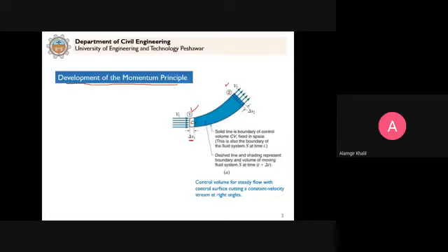You can see here that at time t plus delta t, this is the moving fluid system S. So the system moves and it covers a distance delta S1 at this point and delta S2 at the second point. Clear? So this is the system, as you have defined the system in your fluid mechanics 1. The second thing here is the control volume.